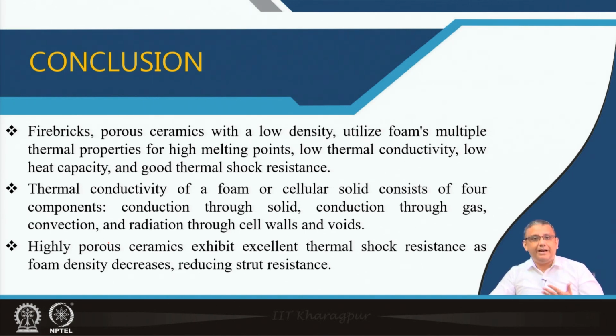Conductivity is a very important parameter, because this controls many applications, and thermal shock resistance is very important especially for porous ceramics, because porous ceramics are brittle materials, and if we put the material to thermal shock, there can be very fast cracking. And that is why we have seen that if we can reduce the relative density by increasing the porosity in the porous materials or porous ceramics, we can increase the thermal shock resistance of those materials.